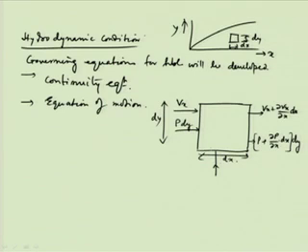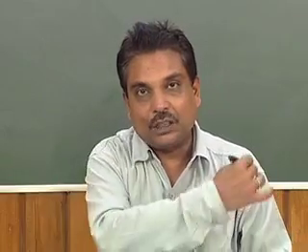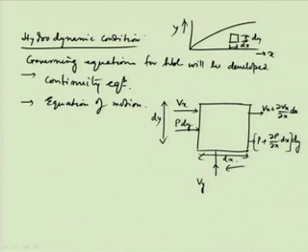So, we will write like this, as if this is the lower layer fluid that is entering. So, it is basically entering with the velocity Vy at that point y, and here we will have a frictional force acting, that is the viscous force that will act against the flow direction. So, this is the flow direction, this layer is flowing in this direction. So, this is the viscous force that will act in this direction, and this is equal to mu into dx, I am sorry, it goes by Newton's law of viscosity basically. So, mu into del Vx by del y into dx, that is the frictional force.